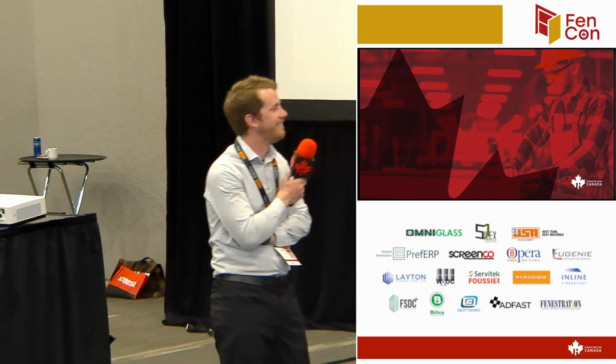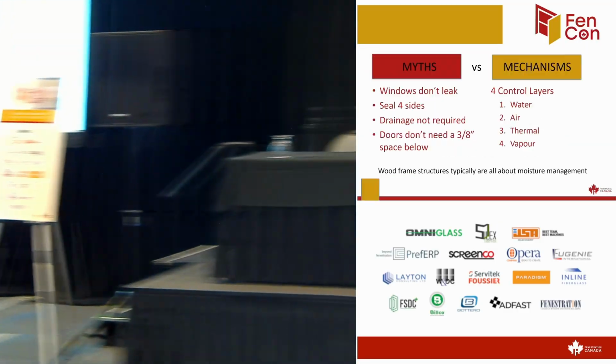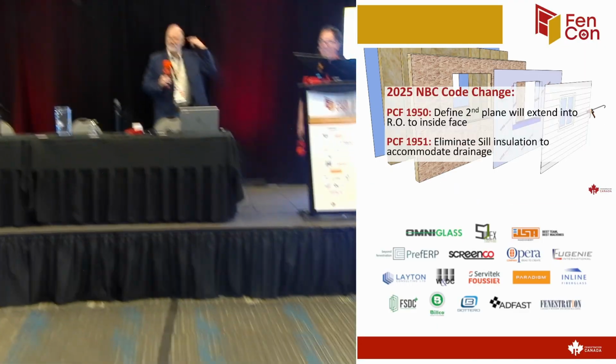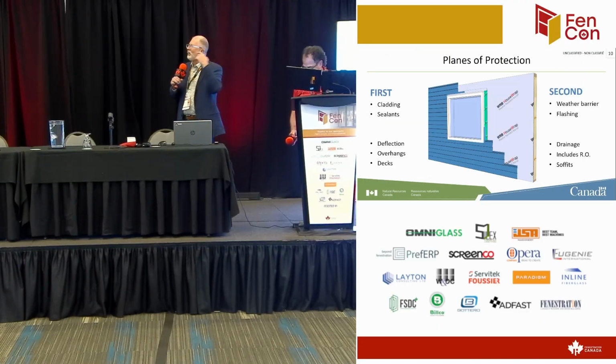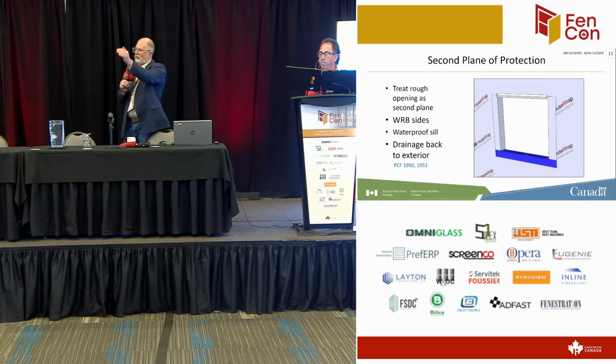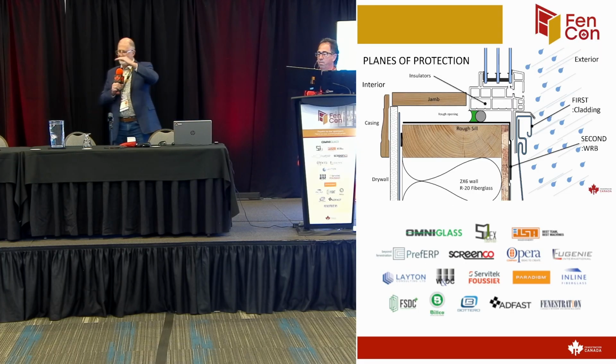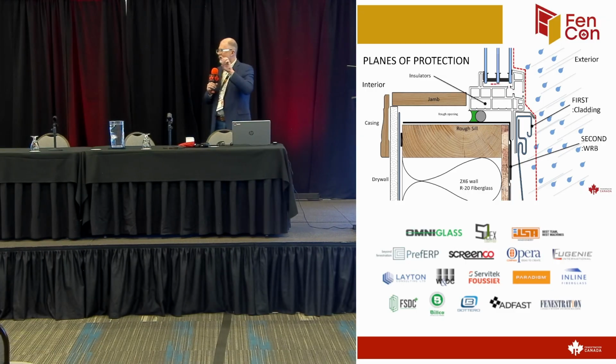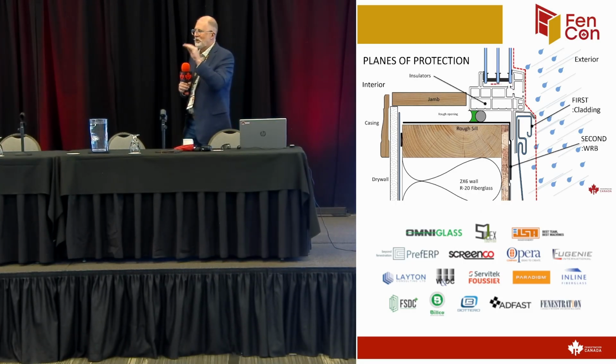Why would I do it? Because I want to sleep at night. And something in the back of my mind says, you can't leave that uninsulated. So I'm not arguing against insulating it, but look at it this way. If I put the sill pan on there and I reduce the air pressure by getting a good air seal, you're right, no issues. I'd still throw mineral wool in there.